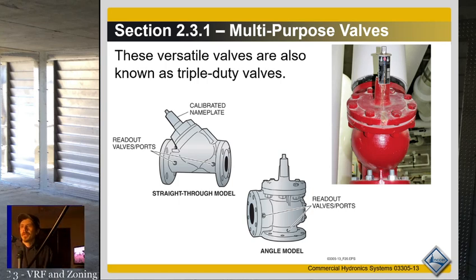Alright, so multi-purpose valves. I'm sure, just looking at the picture, they're talking about valves that are usually shut-off valves and balancing valves, or check valves and balancing valves, things of that nature. The most common one is your triple duty valve, which I don't know if we'll see a slide of, but that is your most common valve on a commercial boiler system.